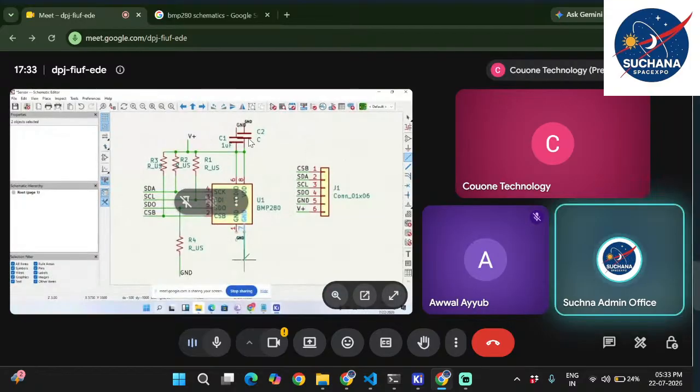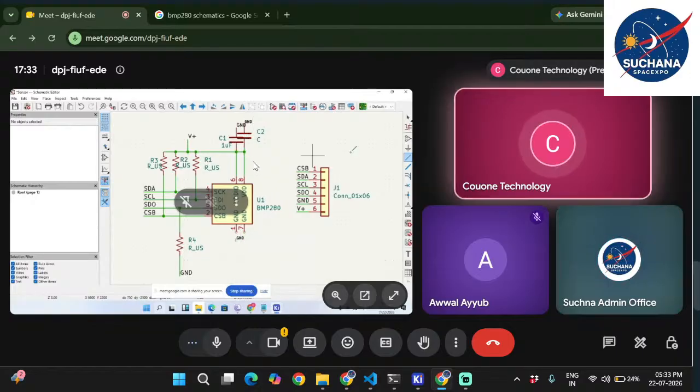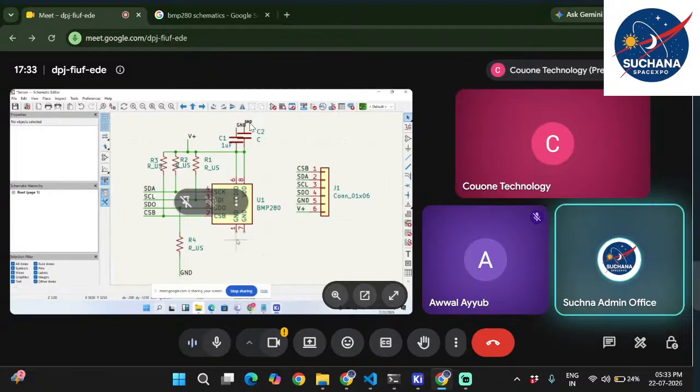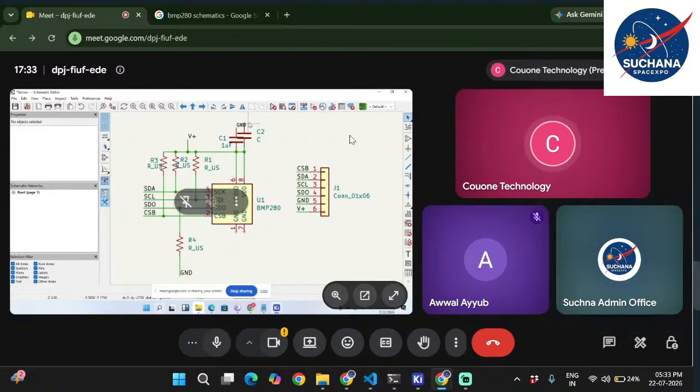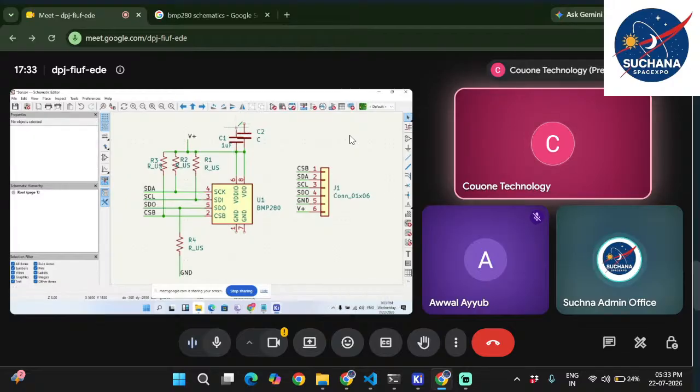I'm talking about the upper surface, where you have VDD and VDDIO. Just delete those net labels and directly short them both.